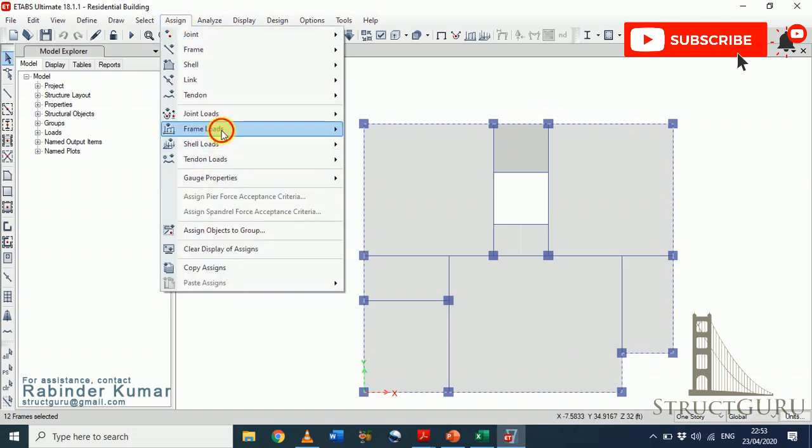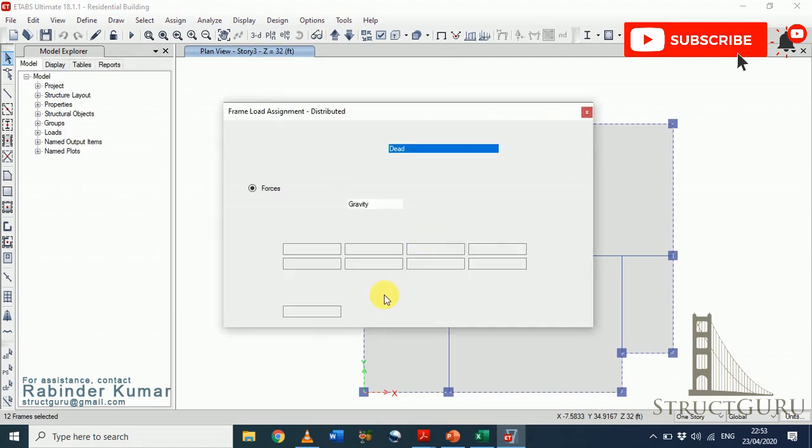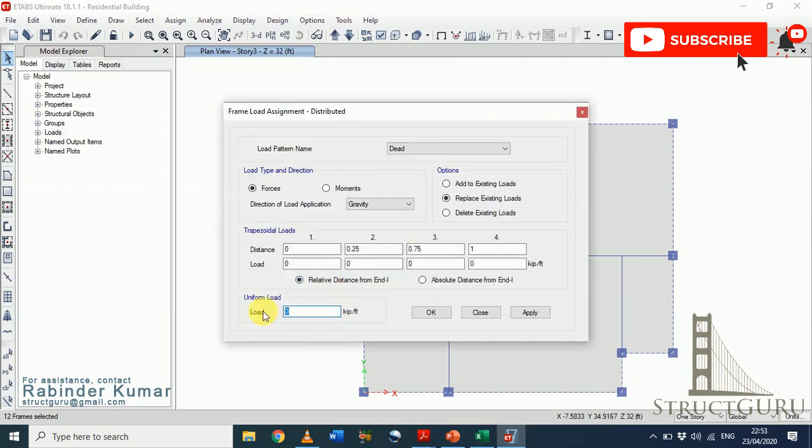Select assign, frame line loads, distributed. So now the wall load will be, the height of wall is 3 feet multiplied by density of cement concrete block multiplied by thickness of wall, which is 9 inches, 0.75 feet. 0.32, click OK.